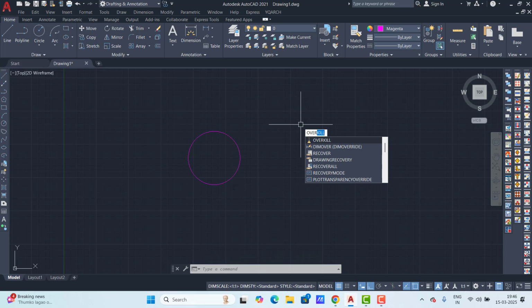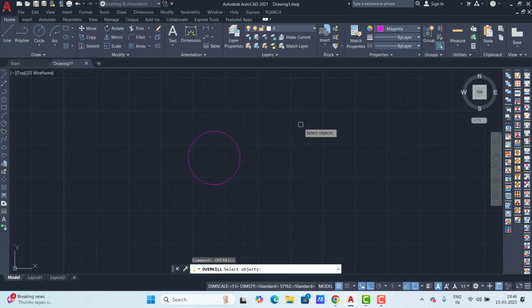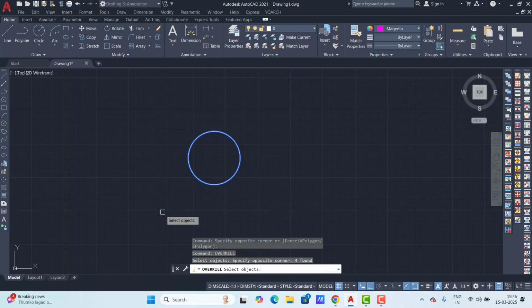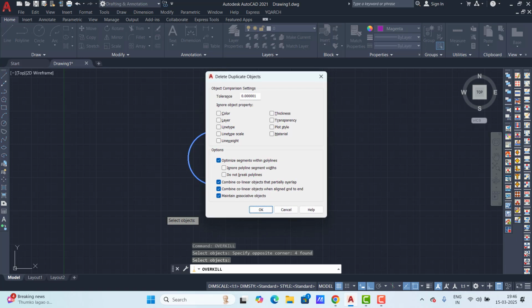Again select any pattern, just select here, and we can use scale factor 50 here. So this way it comes. The angle we can change here to 0. So 0 means that it comes at 45. Okay. Again change the scale factor. Now you see Associative is on. That means this hatch pattern is associative with this line. So in this situation just press OK.